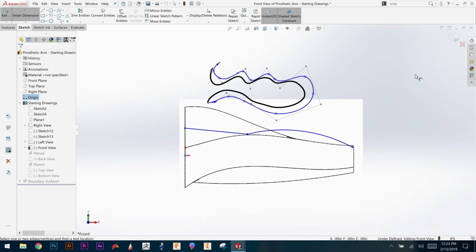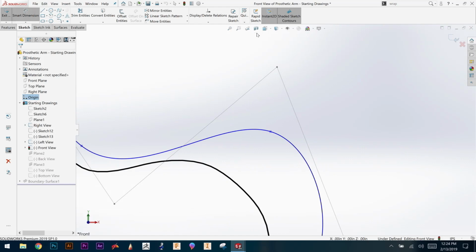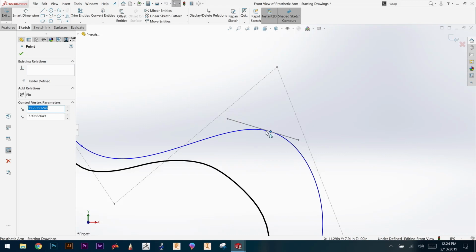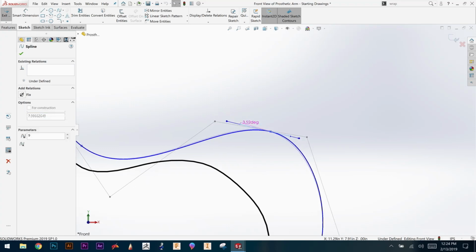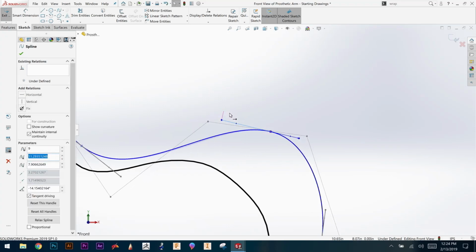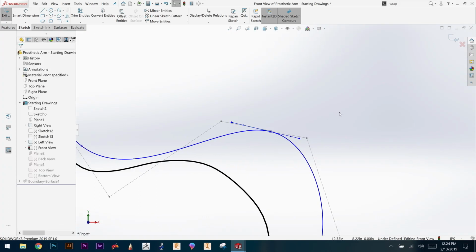Here you've also got the little arrows that you can pull to adjust the power at the ends, and those have a dimension as well from 0 to 1 that you have to key in, so it's kind of impractical. So you're talking about these lines that come off of it, an angle and a weight as well. Right. It has the angle right here and the magnitude with the little arrow. That's the traditional way that a lot of people have gotten used to editing spline curvature, and I've found that it's much more on the technical side and harder to get the end result that you're looking for.